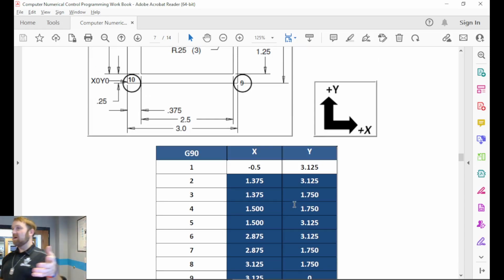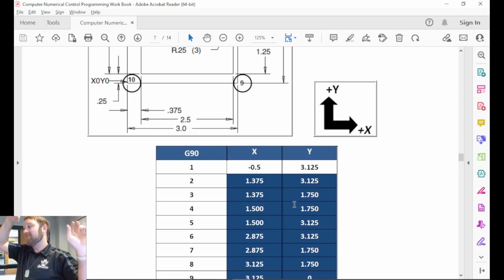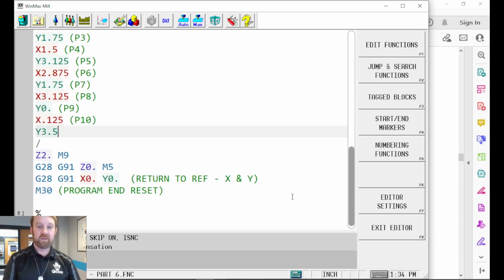And that's what I wanted to talk about when I said whatever I start and end off the part, the diameter of the tool. So I know for some reason they started off the part a 1/4 inch and then they ended off the part an 1/8 inch. Just keep it consistent, do the same thing, make it the diameter of the tool off the part. That way you'll have at least the distance of the radius out of the cut. Okay, just make it the same. You're right for what they had on the thing. Okay, so I'm gonna call that 0.11.